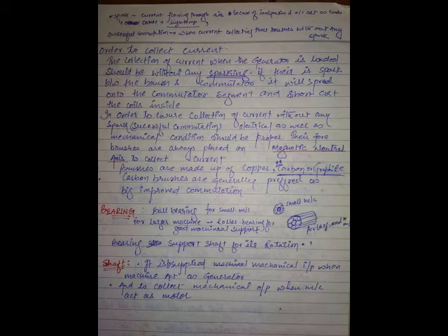will cut the flux. In the first you have written BLV sin theta, across L you have written active length. Active length means the length which cuts flux, only this portion. This is known as the conductor, the length of wire responsible for the induced EMF. The length of wire which is in the magnetic field, which is cutting the magnetic field, is known as conductor. So this is one conductor and this is another conductor, joining at both ends. This is known as one turn.